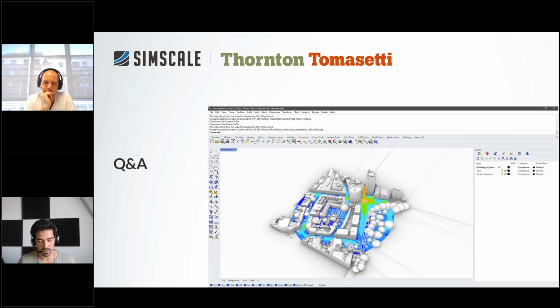On the other hand, the Lattice Boltzmann solver can also be used to scale your resolution as you want it, right? So typically what you have to do is if you want a very low resolution result, you need to ensure your CAD is also compatible with that.